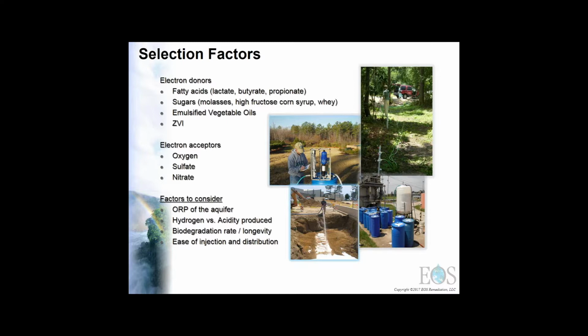And then finally, the ease of injection and distribution. Obviously, if you have a really tight formation, something that's predominantly clay, you may want to think about using something more soluble or something that's going to be much easier to inject, or maybe even considering your injection methodology altogether. And that can be a whole other webinar.